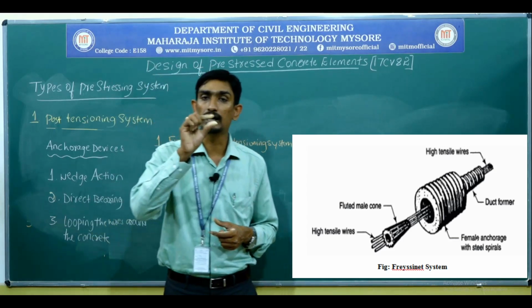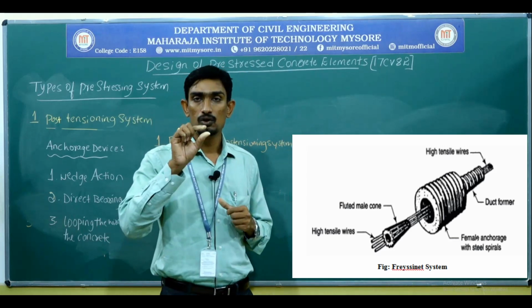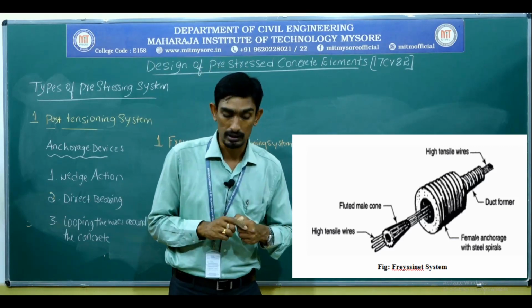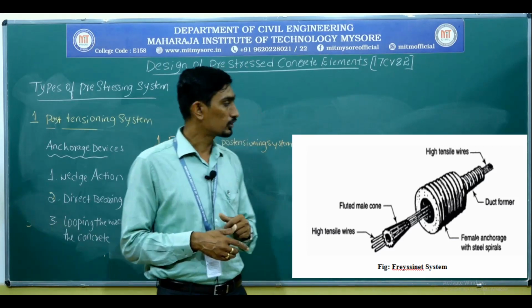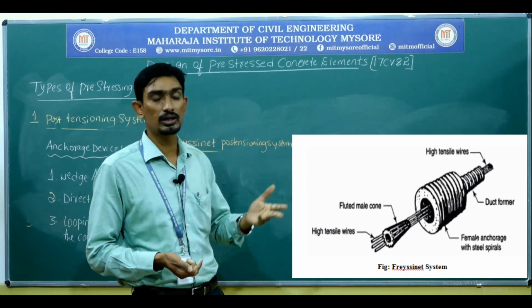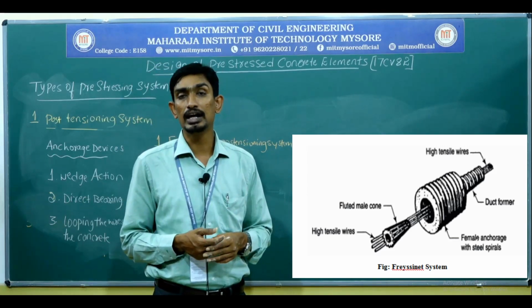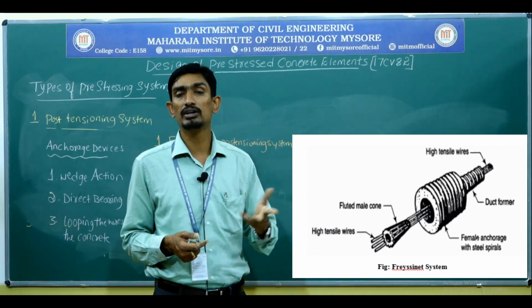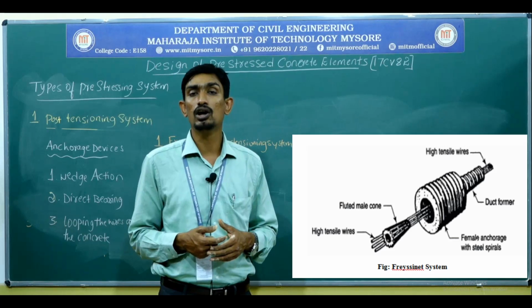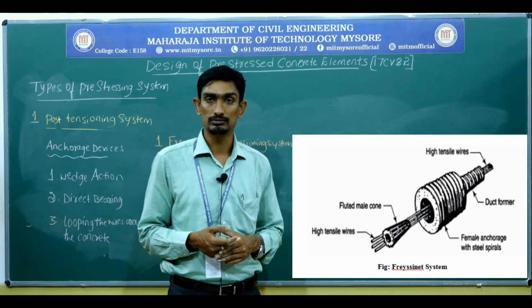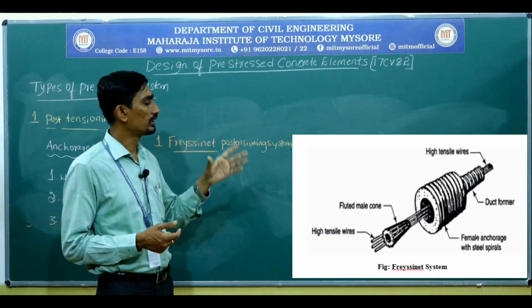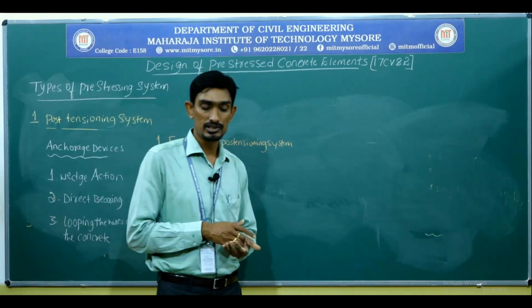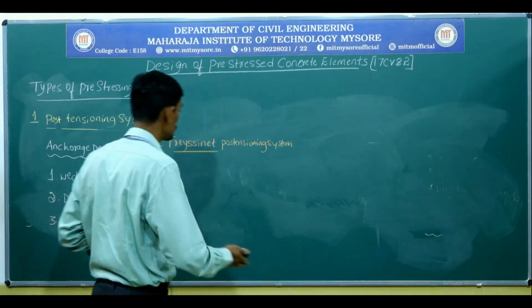Okay, and those conical plugs, or what I can say the wedge, will be anchored longitudinally. Also, through this system we can work with a double acting hydraulic jack system. That means whatever I have mentioned over there, we can work with a hydraulic jack system in order to tension the tendon. So like this, this is the way the Freyssinet anchorage system, or post-tension system, has been developed.